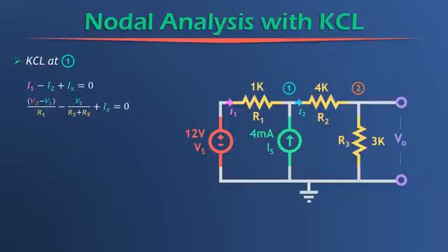Why did we do that? Well, it's because we lumped together R2 and R3 as one resistor, because they are in series, as we learned before. And we can disregard this whole wire flying off here, because there's no current in that wire. It's not going anywhere. It's not doing anything. So you can completely disregard that wire and just call this a series connection of R2 and R3.